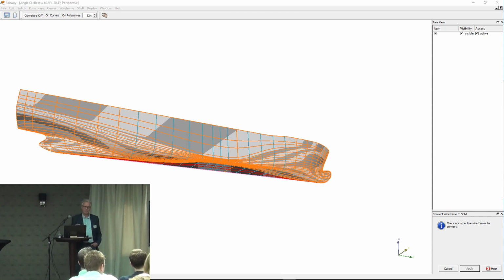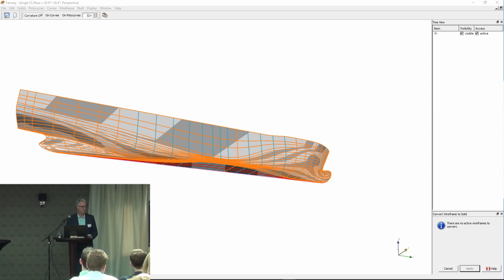So this is one of the most perfect IGES files I've come across. Typically, they would consist of multiple patches, and the lines would not match, or the separation between different parts of the model would not match. We may have double lines or other entities not supposed to be part of the hull model. There may be text in there, there may be loose points, loose lines, etc. We've had models with 36 deck lines at the same location, and that would of course hamper automatic conversion of this. So as easy as it looks, it may not always be.